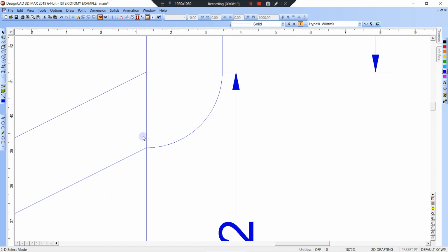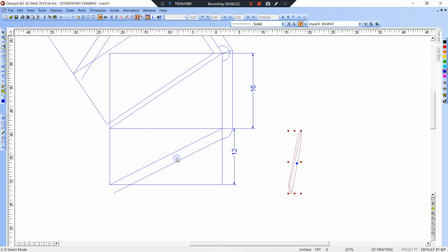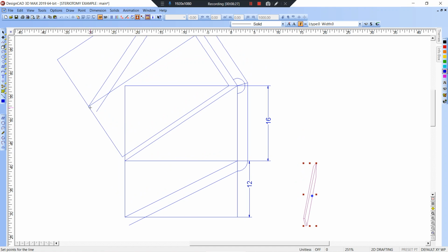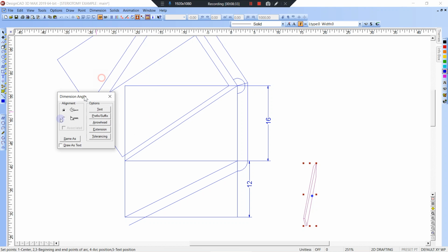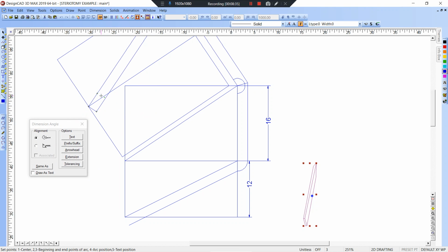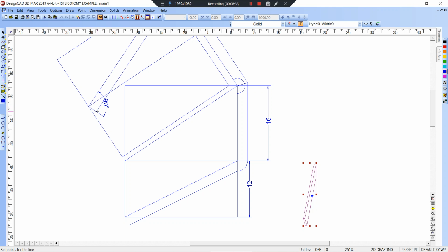So now we know the height of the plumb cut. We've matched the height of the plumb cut, so we know this is a true oblique view of that member. And then we're going to look at this, V, enter, right? So this should be 90 degrees. Right, and if that's 90 degrees, we can transfer this down. So we're using this line, so trim it there, V, we can trim this to that, this to that.